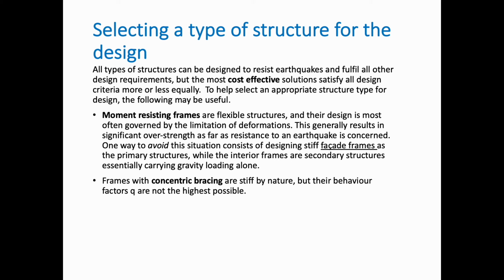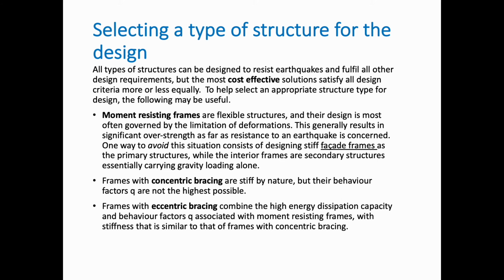When it comes to concentric bracing, these are stiff by nature anyway, but their behavior factors Q are not the highest possible. So we need to add something to it to increase the Q factor and reduce the weight of the structure, the over-design of the structure. Frames with eccentric bracing combine the high energy dissipation capacity and the behavior factors Q associated with the moment-resisting frames